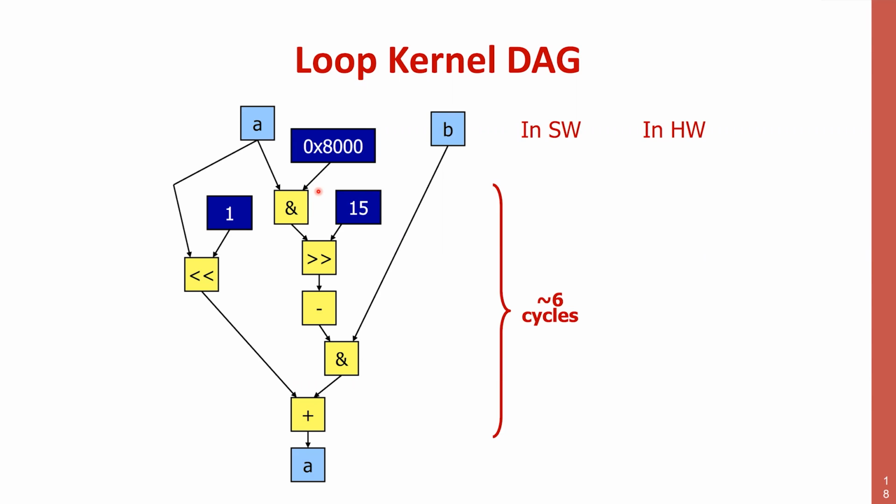But then let's look a little bit more closely. Each of these bits is ANDed by a bit that comes from this operand, and the bits here are either 0 or 1. Now, what happens if I take a bit of A and AND it with a 0? I know the result is 0. So do I need to put any transistor for this?